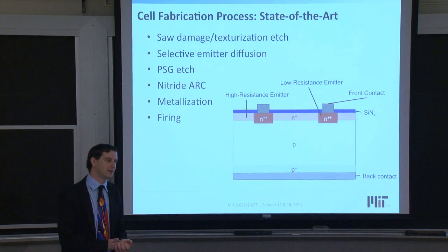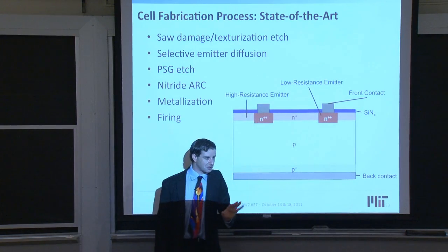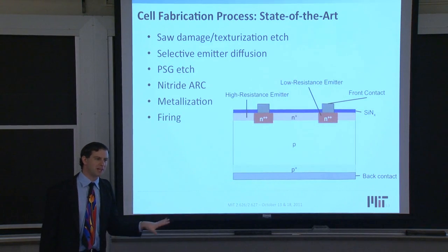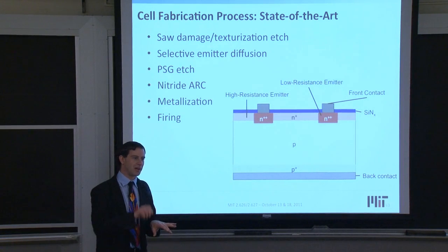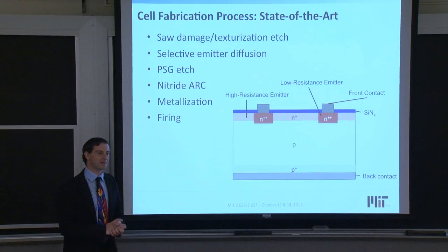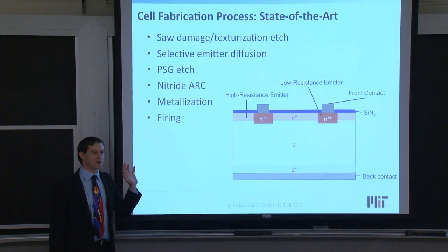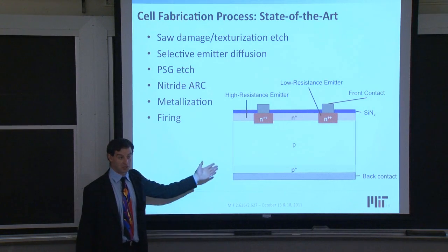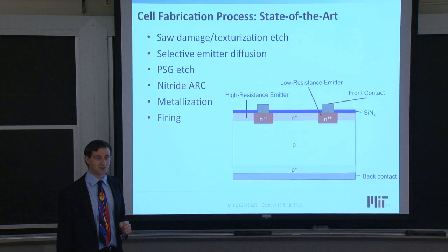And some of the earliest screen printed metallization cells that got in the range of 15 or 16% efficiency only made electrical contact in about 10% of the silicon. But it was enough to have these percolation paths for current to flow up into the metallization. It's a miracle that it works at all, but it's a very effective, cheap manufacturing process that nevertheless is still being used in commercial production today, even among some of the highest efficiency cell architectures.